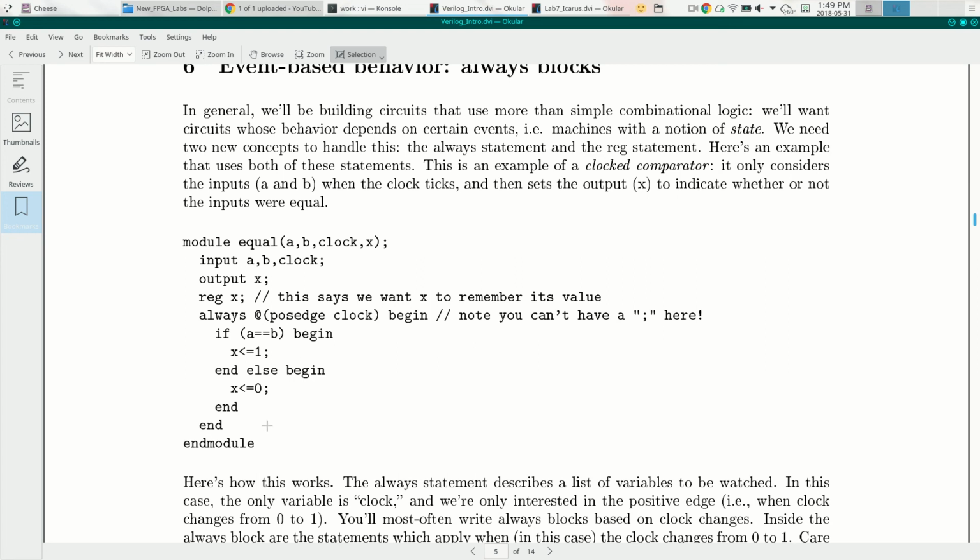But when we work with the Xilinx software tools, Lab 8, after it's compiled our design for us, we can actually say, show us the circuit. And it'll actually show us a schematic for it. And we can also say, show us the equations, and it'll show us the equations. We can say, show us the truth tables, and we can say, show us the K-maps you used. And it'll make all of that available for us.